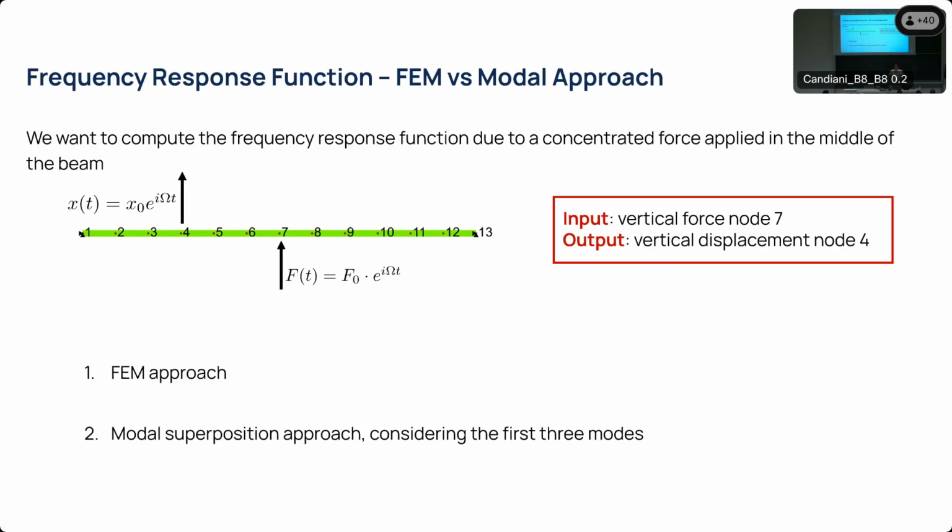So even if we work with FEM, even if FEM is already a simplification of your structure, using a modal approach in FEM allows you to simplify the problem even more by looking only at the specific frequency range and the mode shapes in that frequency range you're interested in, and using the language of the mode shapes to reduce the dimension of your problem and to express the displacement of your structure as the weighted sum of mode shapes, so only the mode shapes you're interested in. This is very useful, especially when you have very big structures or very small frequency ranges.